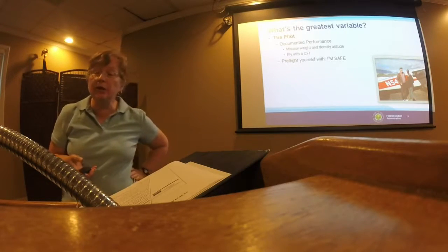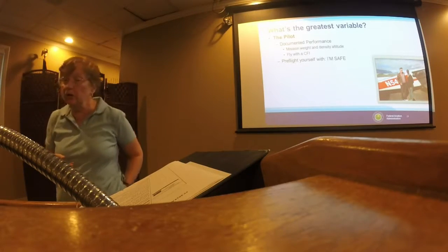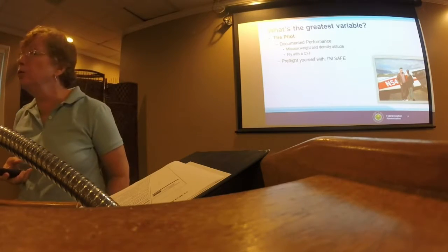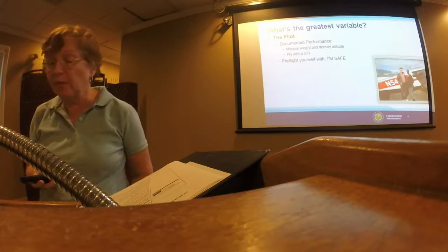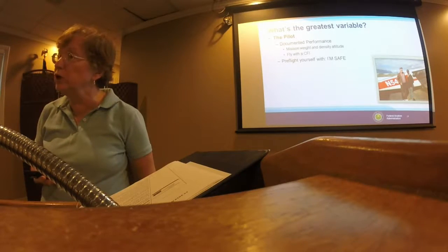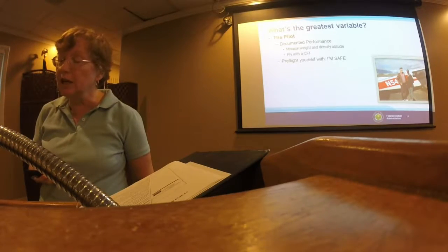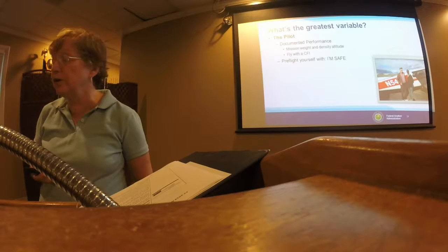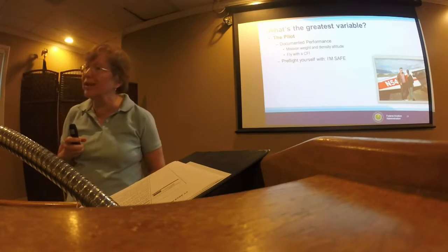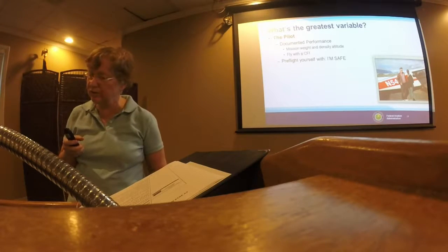Once again, the pilot is the greatest variable. But if you fly often, document your baseline performance at your usual mission weights and density altitude, and fly regularly with a flight instructor, you're well on your way to getting close to those figures.